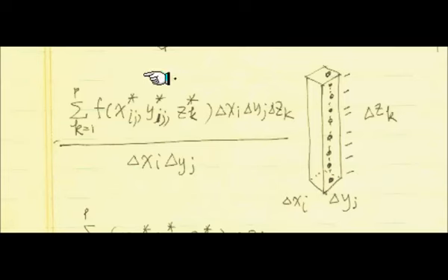So the whole thing, if you sum over k from 1 to p, is going to be the total mass. And that total mass's magnitude is exactly the force that is exerted onto this bottom plate, which has area delta xi and delta yj. Pressure is the total force applied to this area of the bottom region, so if you divide by it, that's going to be the pressure.